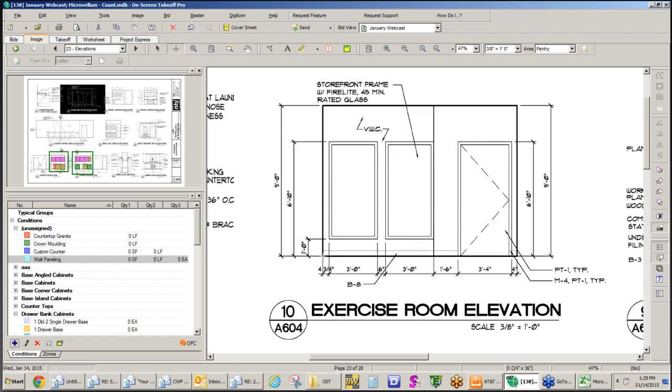So I'm thinking about this being wall paneling, and so I'm going to click around the perimeter of what I'm doing here, and I'm going to even go around the doorway of this, and then we'll finish out. So now we have that calculated. I even want to be able to back out where we're doing calculations for this to tell it that I don't want to calculate the area where the windows are located. Try not to zoom too far for what we were doing here. Okay, so I did the back out.